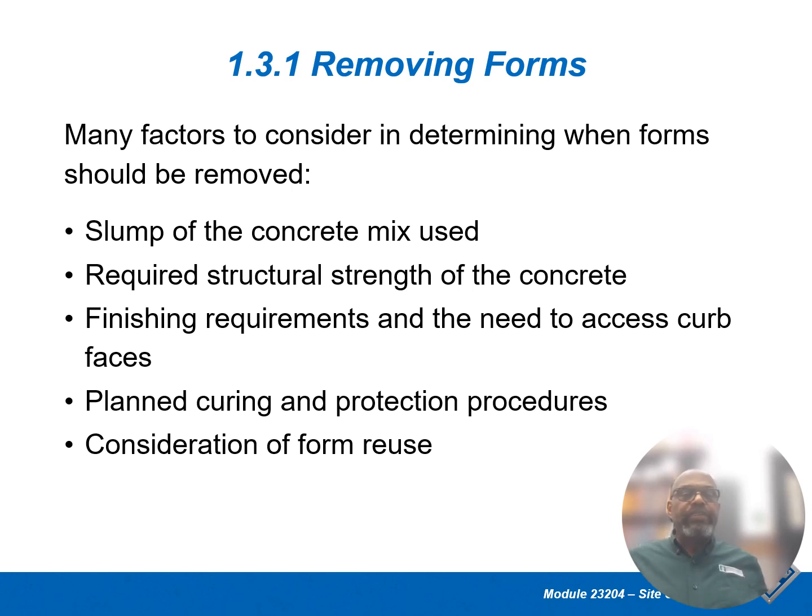There are many factors considered in determining when forms should be removed: slump of the concrete mix used, required structural strength of the concrete, finishing requirements and the need to access the curb faces, planned curing and protection procedures, and of course, considerations of form reuse.